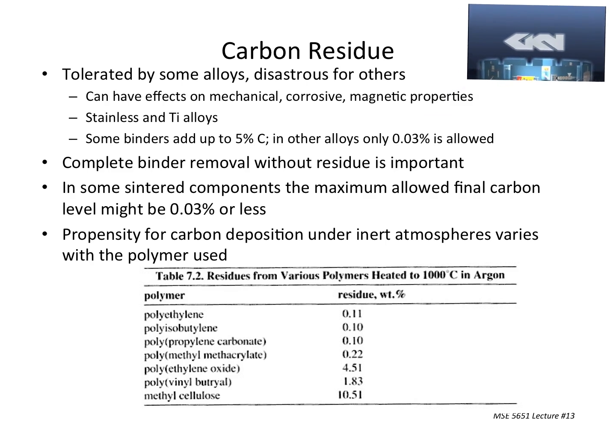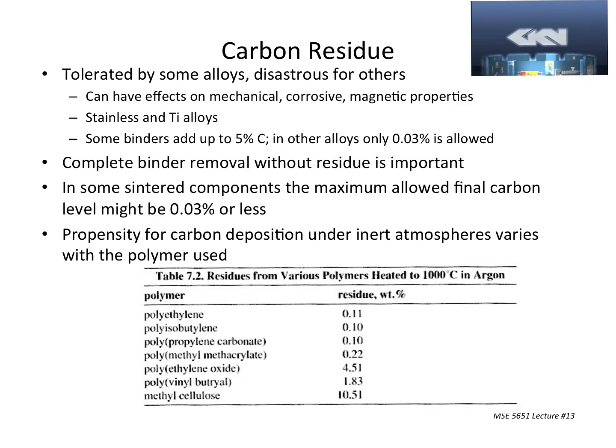Questions about carbon residue? Bless you. It's tolerated by some alloys. It can be disastrous for others. The carbon can have effects on mechanical, corrosive, and magnetic properties. Now, sometimes we want the mechanical properties. All right, carbides help us there.